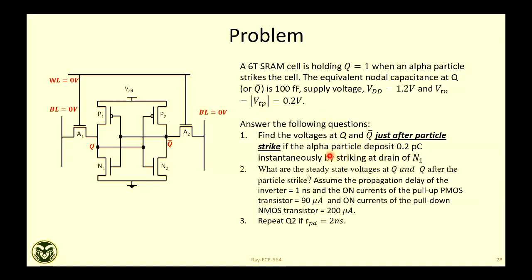So your alpha particle is emitted, right? Alpha particle can come from packaging material also. The ceramic that you use to package your chip can sometimes emit alpha particles, given that it has some radioactive element inside. As I said at the beginning, this issue was first observed in the 1970s in DRAM, in Colorado, where some mine water was contaminated with radioactive material. A very tiny fraction is good enough to cause upset.